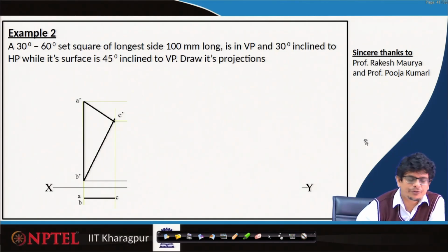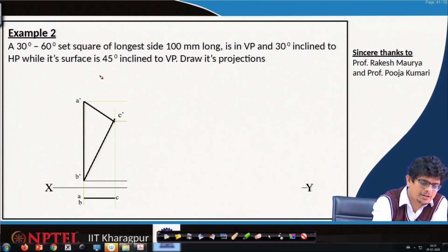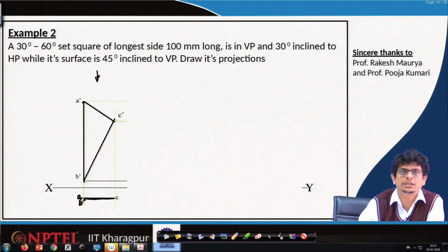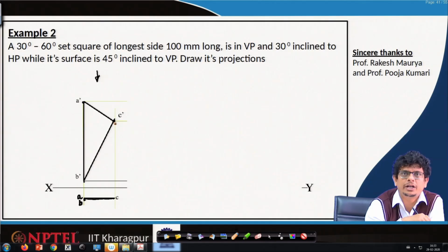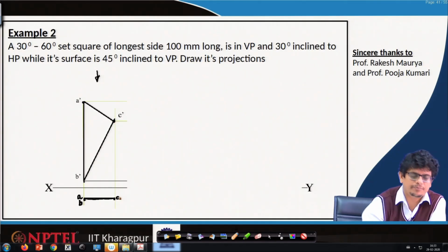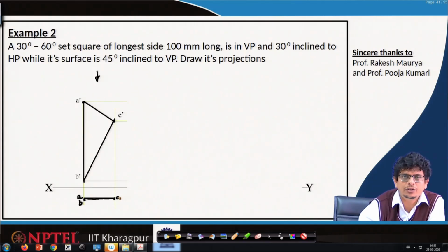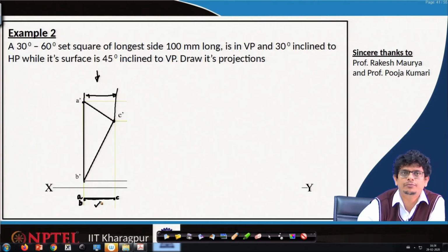If we are looking from top view of this frontal plane, from top view, it looks like a very thin strip, where A, B coincides to A and B points. Similarly, this C point, C prime, whatever we are looking at in the front view, is projected all the way to C. So, the actual length that we are going to see is this projected length, that is, we are going to see it in the top view.